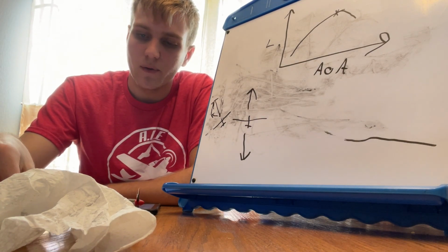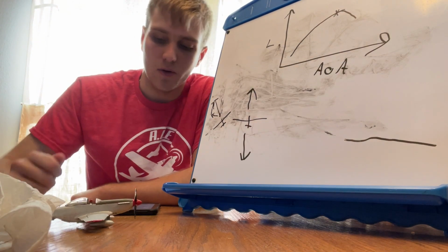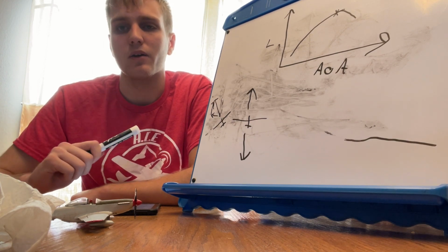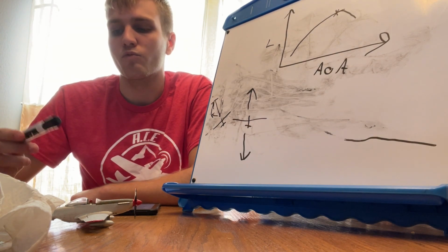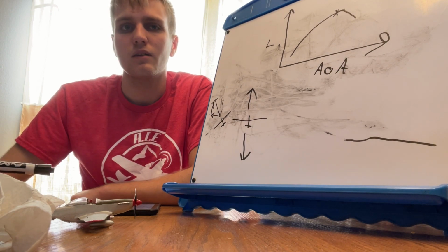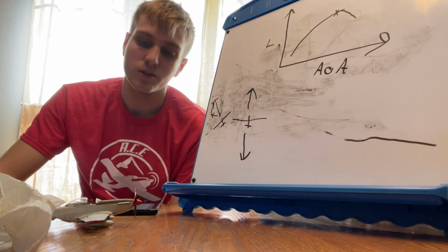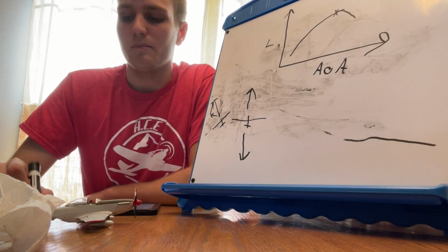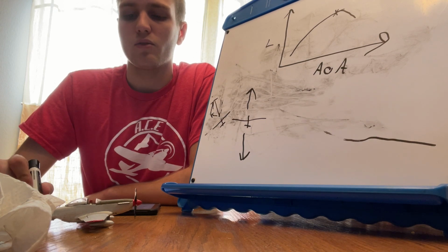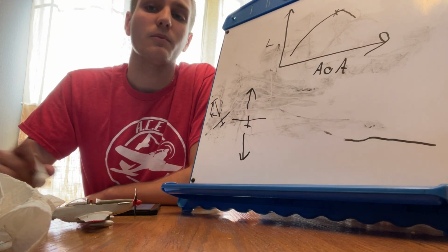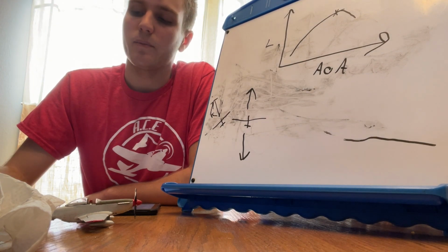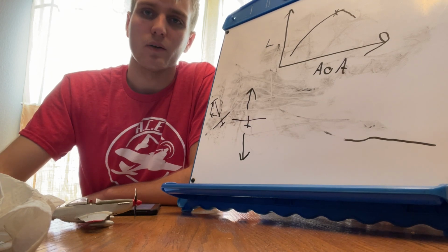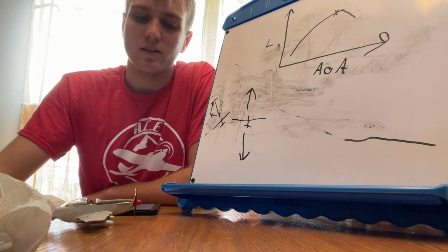If I were to ask you in front of me, I'd ask this. If our baggage compartment says it's a max weight of 100 pounds, and our airplane is rated for a load factor of 4 G's, if we put 100 pounds of weight in our baggage compartment and we pull 4 G's, that bag is going to weigh 400 pounds. Would that be exceeding the limit of the airplane?